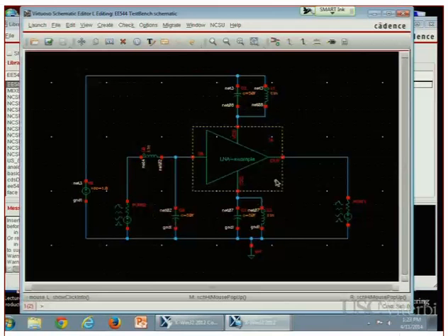And so this is an example of a test bench. It consists of the input port right here. This part right here would be a parasitic network. I have parasitics on the ground and the power as well, so that's something that you'll have to deal with. If you're designing a circuit that has source degeneration, this will be part of your source degeneration network.